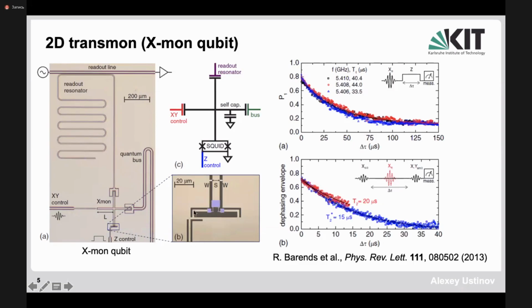And the Josephson energy of this composite junction is controlled by the magnetic flux produced by current which is sent in this middle wire at the bottom and then extracted to the ground to the right. So this current generates magnetic flux in this loop, which contains two Josephson junctions and the upper electrode, these blue fragments which you see on the right inset.